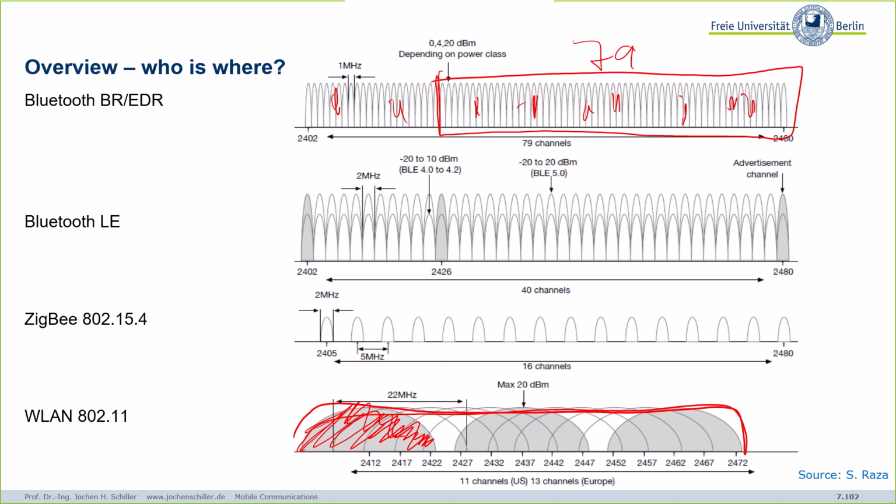So this is also why it's a good idea to have the wireless LAN at 5 GHz, or maybe in the future 6 GHz. Then you are far away from all this Bluetooth stuff and not using wireless LAN at 2.4 GHz. So that's one of the ideas, because 2.4 is too crowded. It's extremely crowded. And then you have Zigbee in addition, etc., etc.